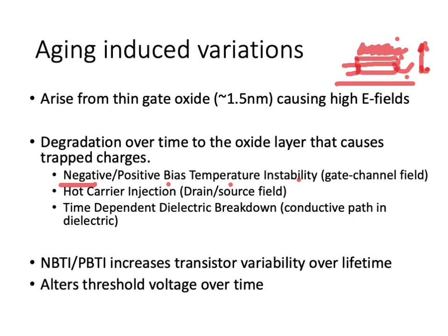It would actually change the entire die's performance over time, and this would be more due to hot carrier injection and TDDB, but it also increases the variability of delay performance between individual transistors, and this is due to NBTI and PBTI. So these are aging-induced variations at the transistor or logic gate level.